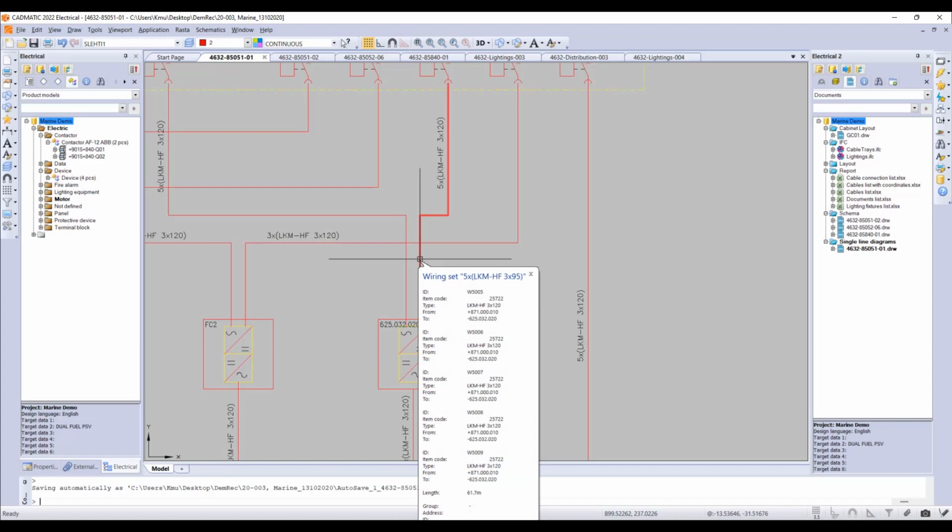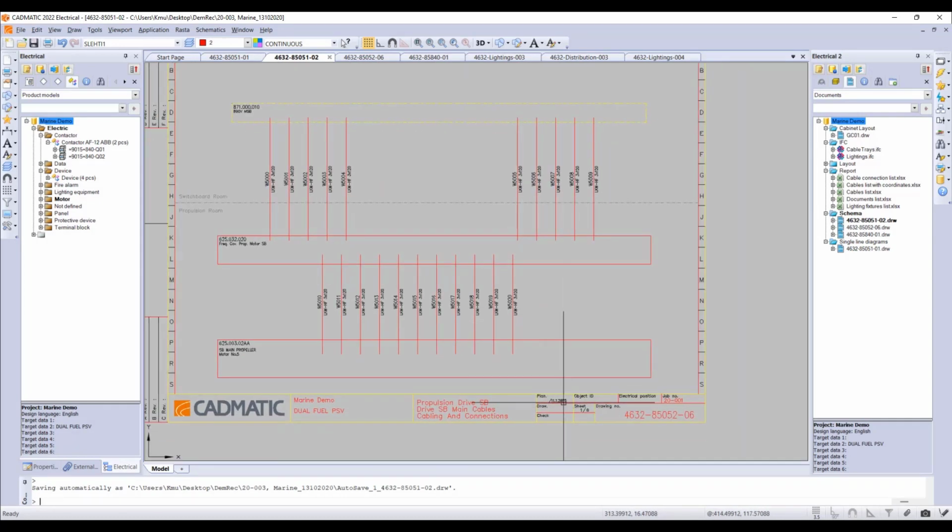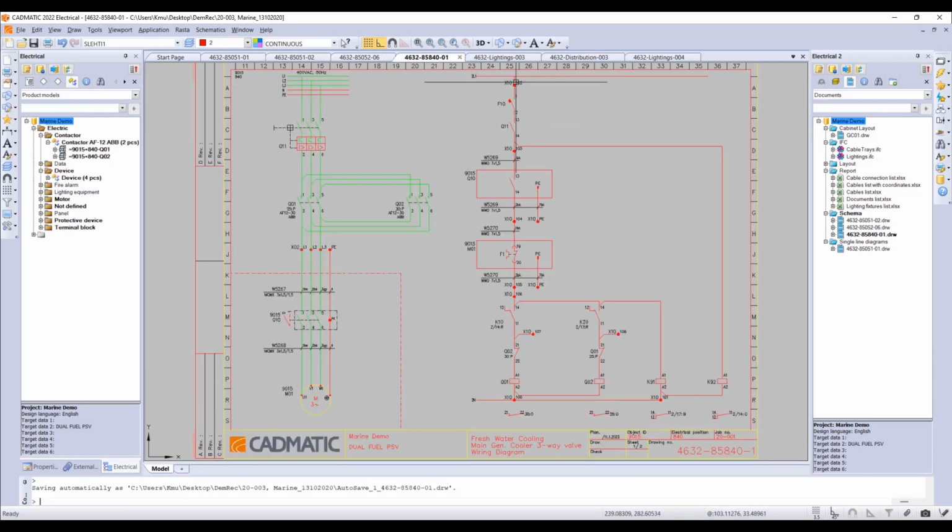The cable IDs are updated, the cable packages, but also here in the block diagram, the cable IDs and cable type information is updated. So you don't need to open up the documents to make changes. You have always the database tool that supports you in doing that.